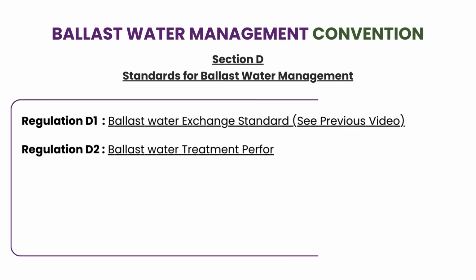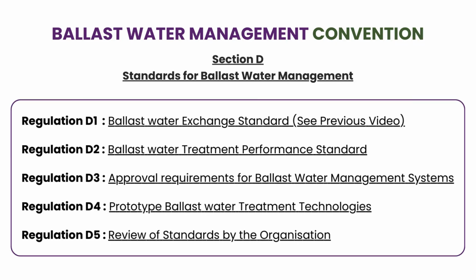The Ballast Water Management Convention, which has been updated, covers regulation D-1, which is the Ballast Water Exchange Standard. You can see that in my previous video. Regulation D-2, we are covering partly in this video. D3 is the approval requirement for ballast water management systems.